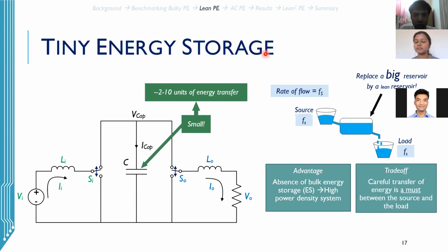Yeah, one is the application, the other one is the PWM itself. For example, if you have continuous currents on one side of the power converter and you have switching currents on the other side of the power converter, it's the capacitor which is actually taking the ripple. Right. Yes. And the value reduction that you are saying is theoretically true if you don't consider the current stress that the switching ripple is going to put on the cap. But it's actually a multi-constraint problem, right?